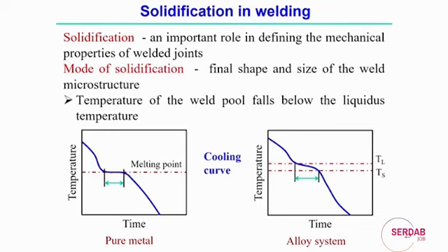That graph clearly shows a phase change over time from liquid to solid, and gradually in the solid state there is a considerable decrement of temperature. So this is a typical solidification curve in the case of a pure metal.